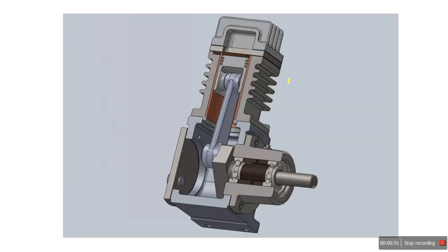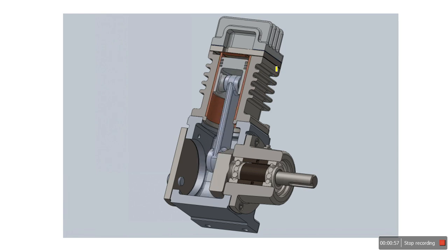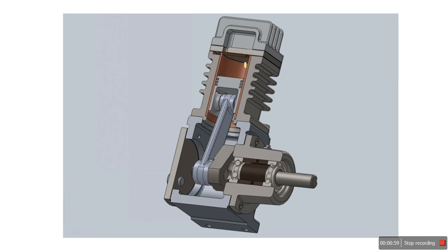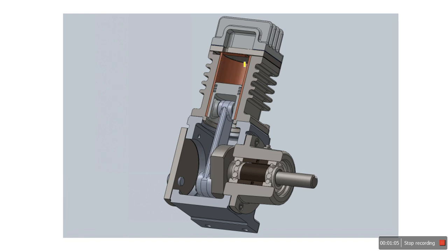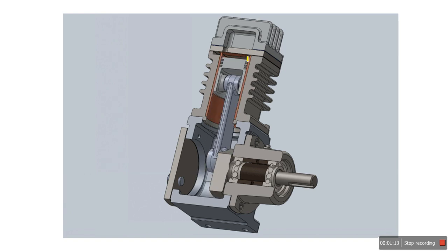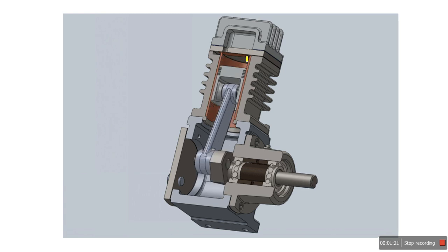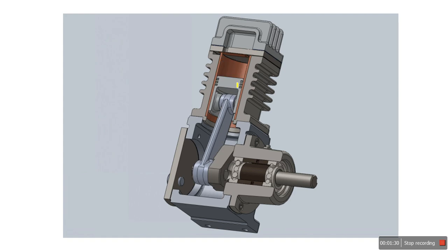We also discussed the need for air cooling, because if proper cooling is not there, the volumetric efficiency of the compressor goes down. Volumetric efficiency depends on the volume sucked during the suction or induction stroke. Because of heating in the inlet valve or intake manifold, the air in the cylinder increases its volume, so the mass of air coming in during each induction stroke is less. This affects volumetric efficiency, so we need proper air cooling for low capacity.